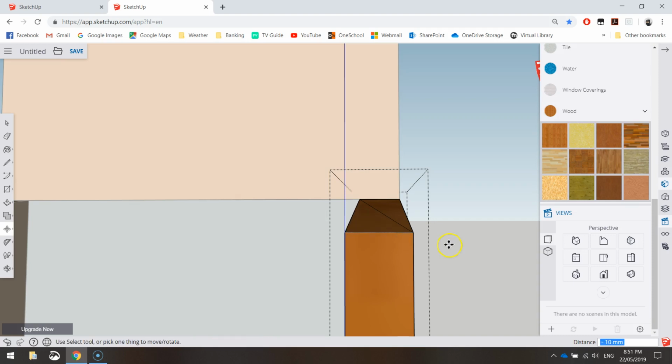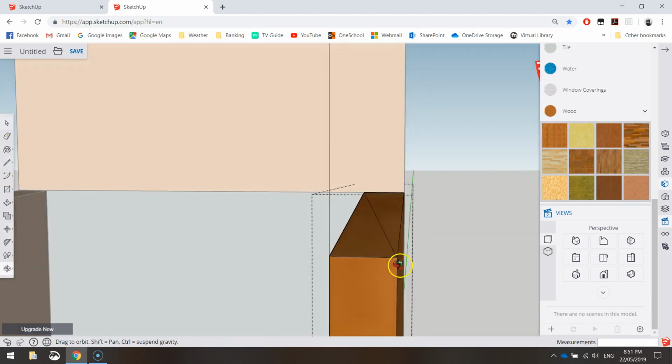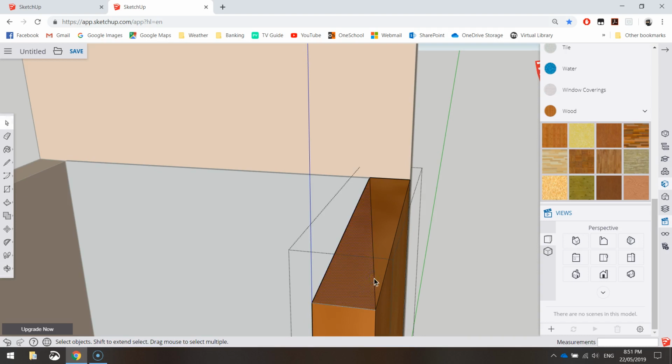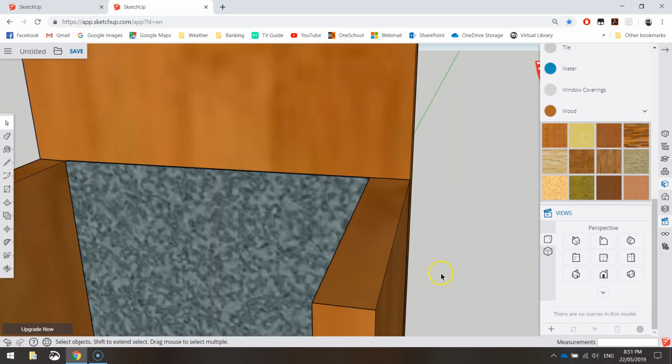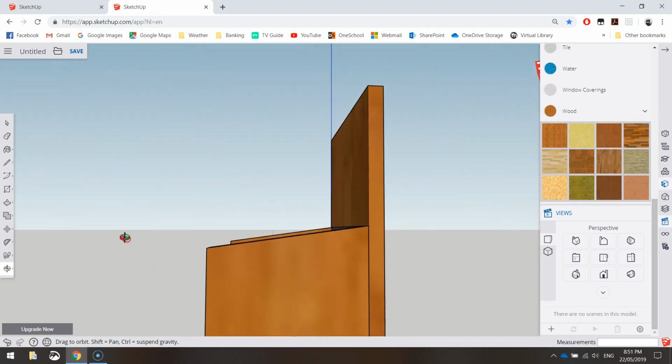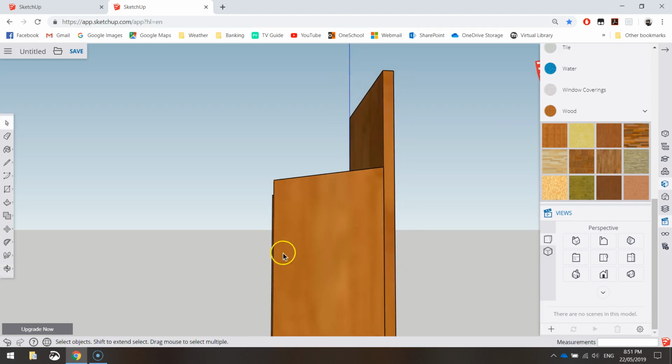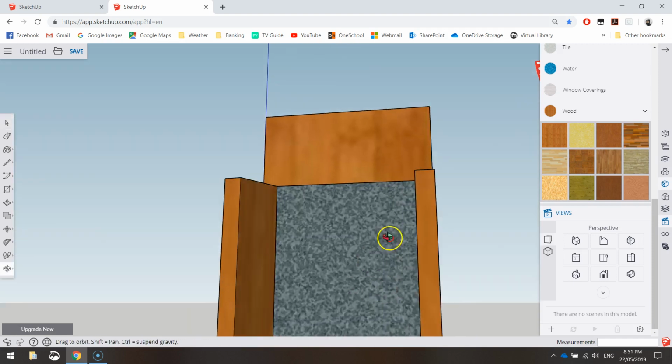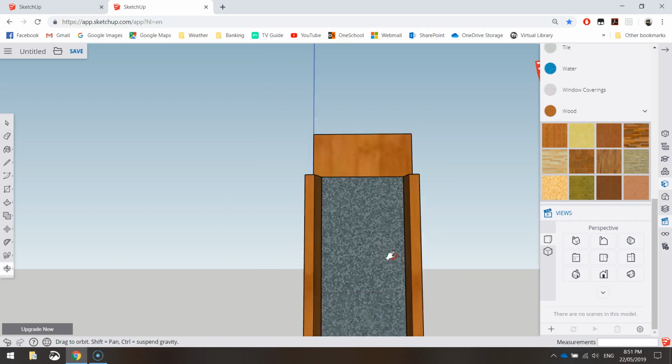It's level with that line. Grab your arrow tool, click on this black line on the top, whatever that is, and press delete. Click outside of your shape, and then click once on the black line we just drew and press delete on your keyboard again. Okay, so we've now got these sides on an 8-degree angle, which is going to allow us to put on a sloped roof, which will prevent the rain from running onto our bird box.